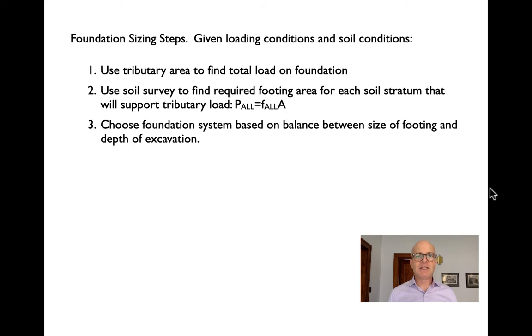So how do we size foundations? We take the tributary area, we use the same process that we use for column loads. We take the load usually on that last column, right down at the first floor, and we get what the total load on the foundation is going to be. We get the soil survey from our geotechnical engineer. We go through and we can figure out what the size of the footing is going to have to be at each stratum, right? So we're going to need a very big one if we want to rest the building on organics, a slightly smaller one if we want to rest it on clay.